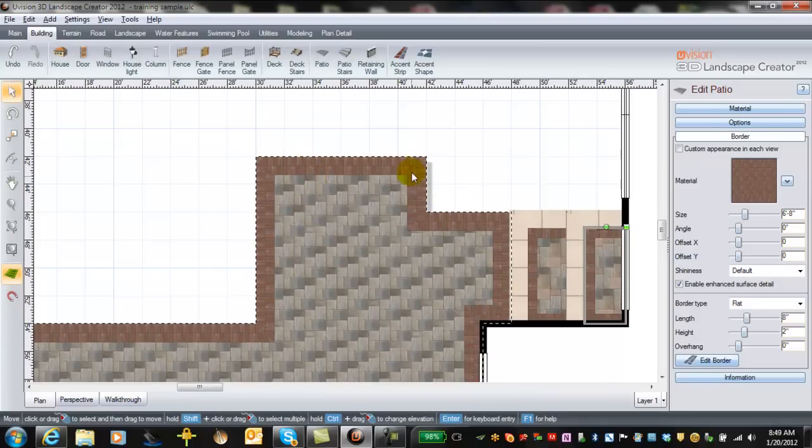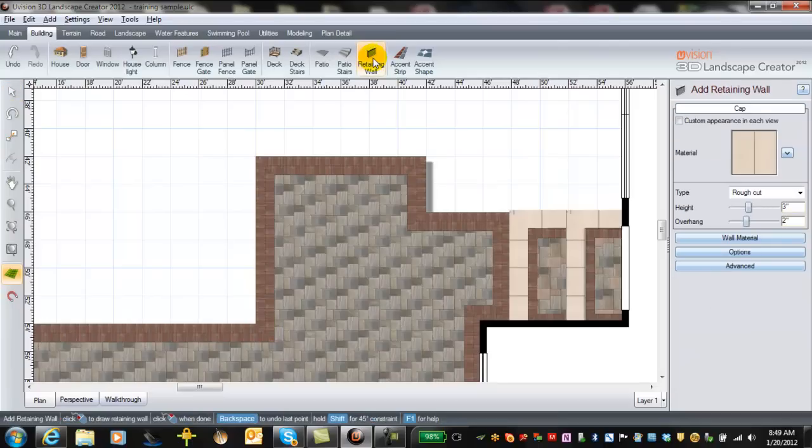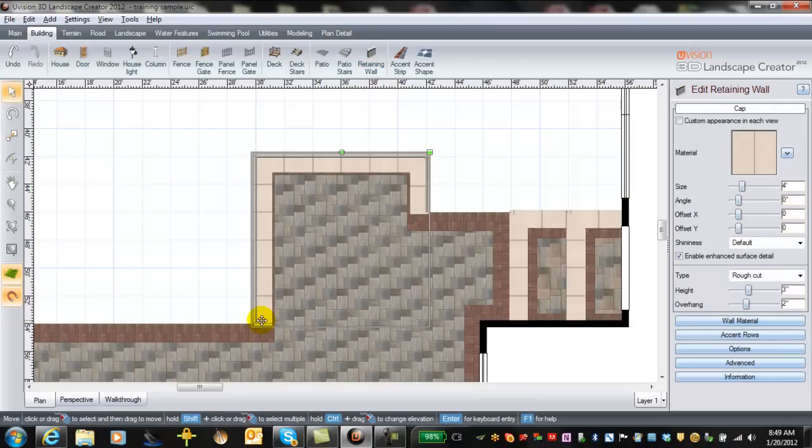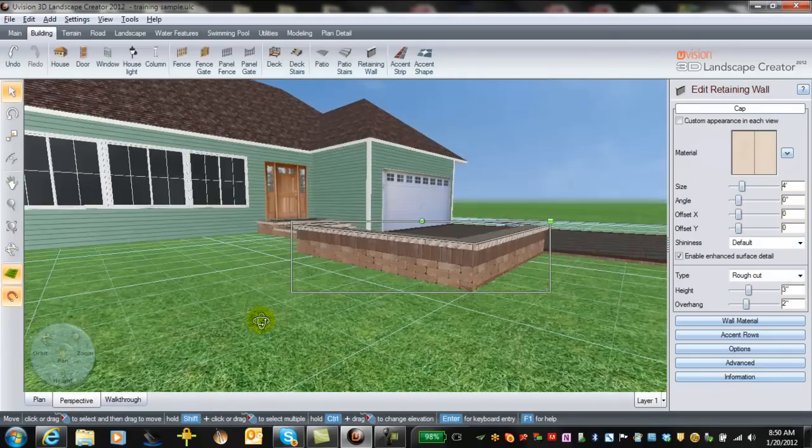So we're going to go from here, here to here with our retaining wall. So let's click on that. And I would recommend the snap again, especially if your original design was built with the snap in place. Then you can see how the dot snaps nicely into corners. So we're going to start here with our wall, go along here and to here and to here, and then we're going to right click and so you can see our wall that's into place, our seat wall.